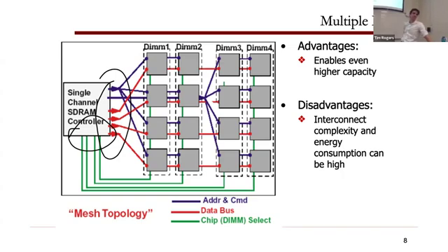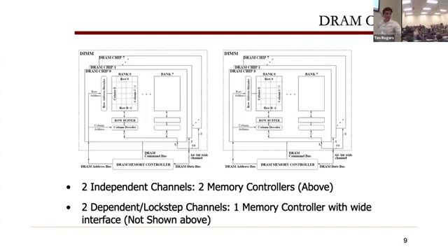Other questions? All right. Okay, so that's a single channel system. Even CPUs can have more than one channel, right? If you've got one of these Intel processors in a data center that's got like 80 hardware threads on it, that's a lot of memory demand, even from scalar processors. And you'll want to have more pins coming out of the chip and more memory channels to deal with it. It's not like a GPU where we have like 32 memory channels, but you can have 4 memory channels on a CPU system.